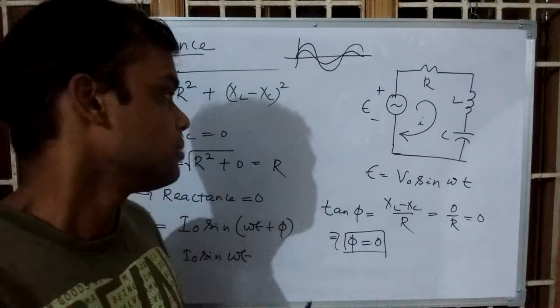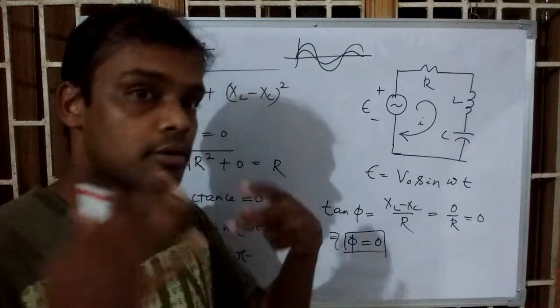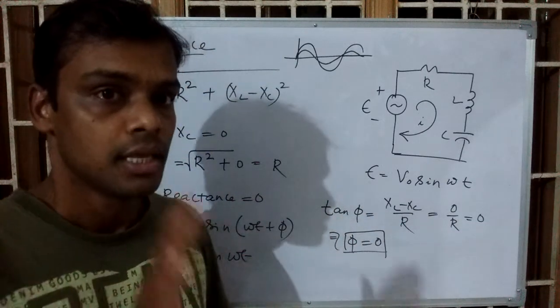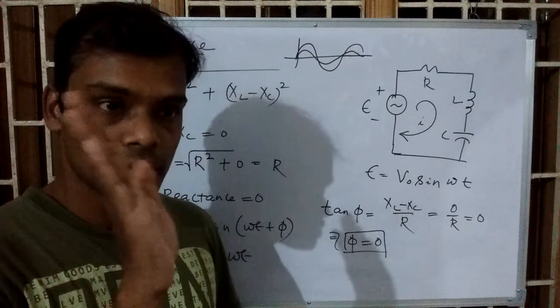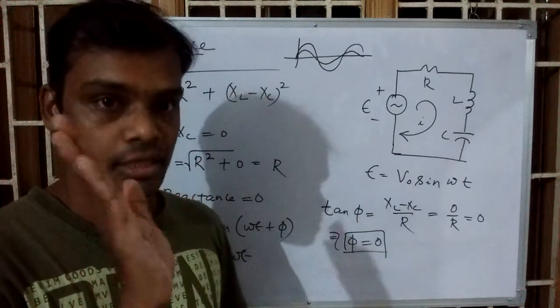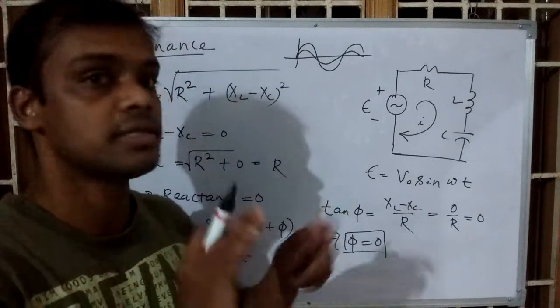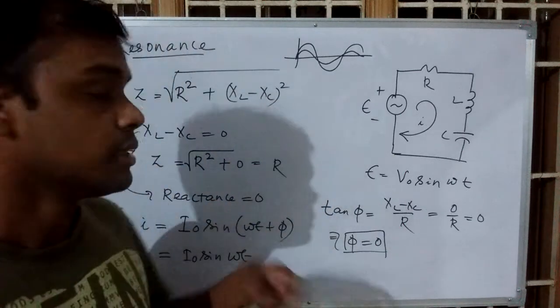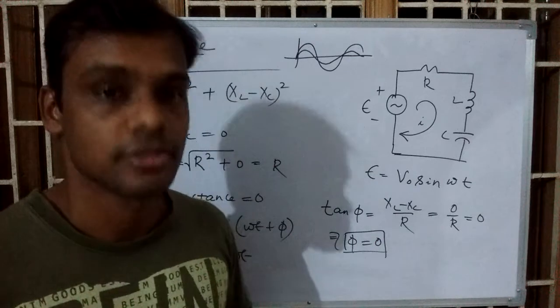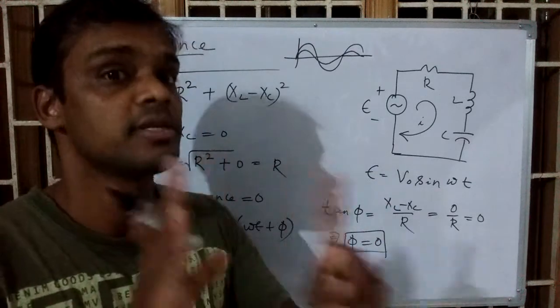And if your hitting frequency is equal to that natural frequency, the amplitude keeps on increasing gradually, only because the frequency is matching. In that case you say this is a resonance condition, because frequency is matching.